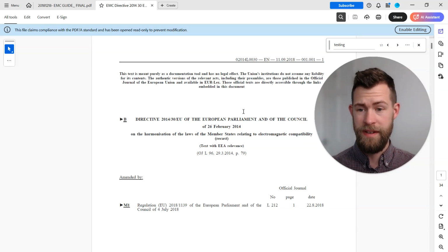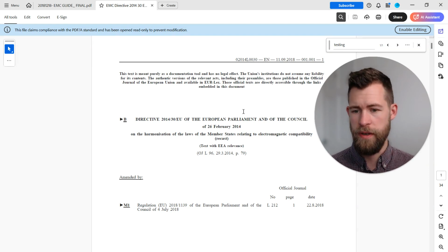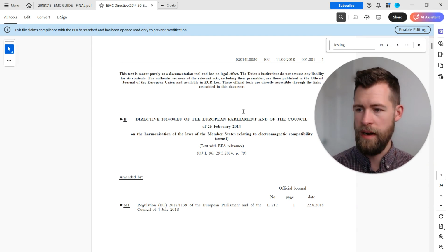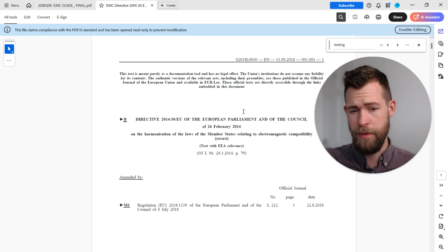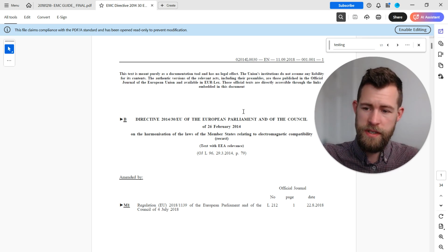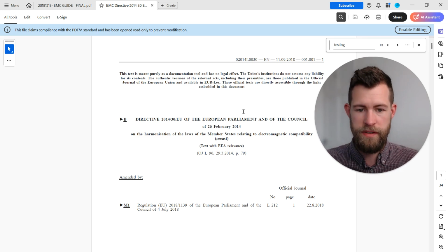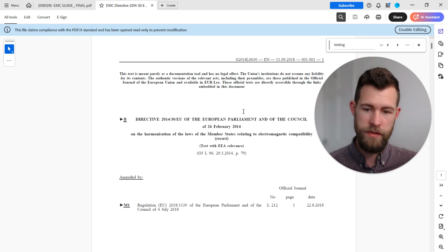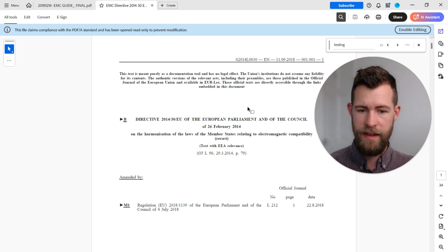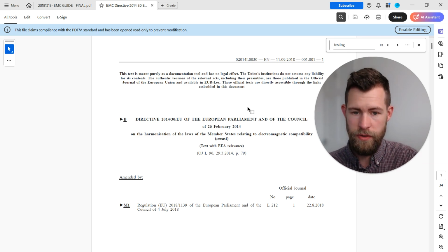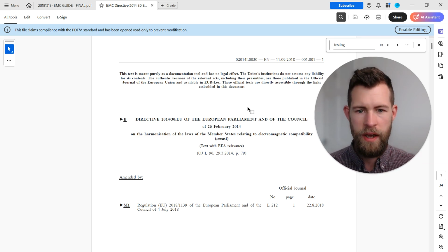So I'm going to talk about the EMC Directive briefly. I often start conversations with potential clients around what legislation is applicable to their machine. And one of the questions in there is around the EMC Directive. Typically it's applicable if you've got machinery that's got electrical devices in, it's either going to be emitting EMC noise or it's going to have a susceptibility to electrical noise from other machinery.